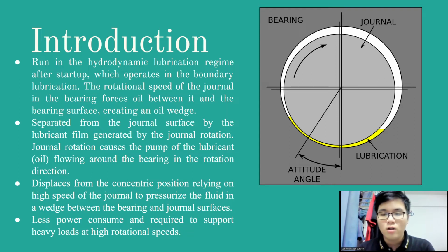The pressure falls to the cavitation pressure in the diverging gap zone, where cavitation forms. This system is popular because it consumes less power and can support heavy loads at high rotational speed. And since it consumes less power, it is more efficient and high precision.